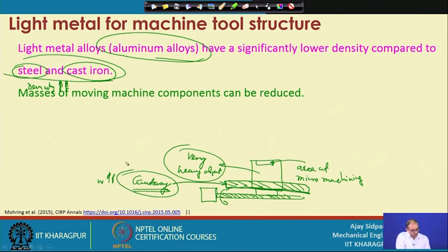So, in this case when you are moving this by lead screw, the motor will be loaded more, because it has to provide such a high torque so that it can move this object in different directions, maybe to and fro or left or right depending on your axis. So, when you are doing this, you cannot get a very fast movement, that means your feed rate will be very low.